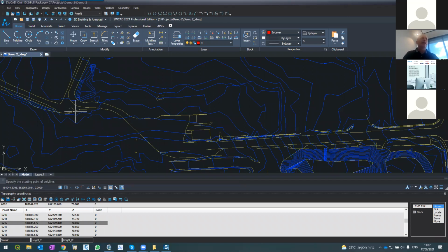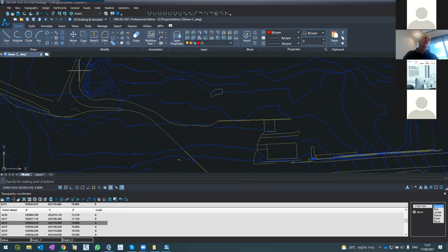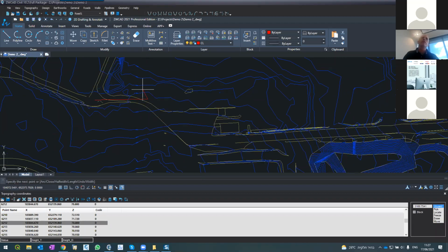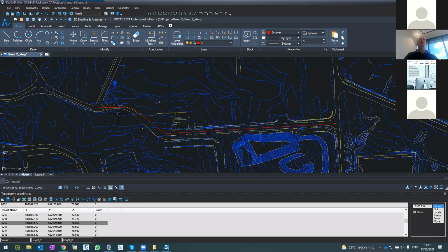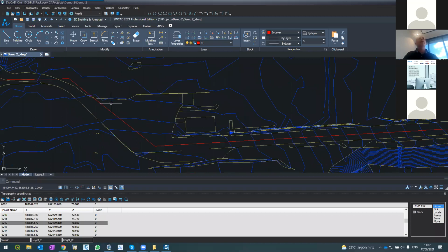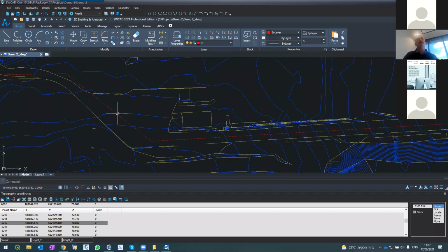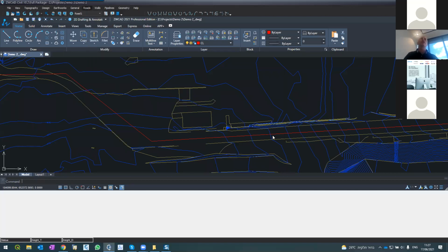And I'm starting from this B junction, say here, going here, somewhere here, and from here all the way to this point. So this is my to-be centerline. But for now, it's just a 2D polyline. So what I want to do is create a beam of a road out of it. And of course, the first element is the horizontal alignment. So I'll go to the horizontal alignment.